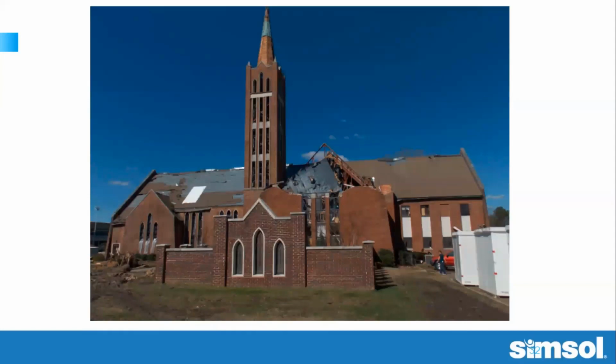Let's take a look at this one. This is again a nice church. Obviously, it's got some issues with the roof, and you see some windows blown out there on the left side. Take a look at the steeple on the church. I don't know if you can see it real well, but if you notice, there's a lot of the greenish colored copper flashing missing from the steeple. I can tell you from experience that there's about 65 to 70% of the copper flashing missing from that steeple.